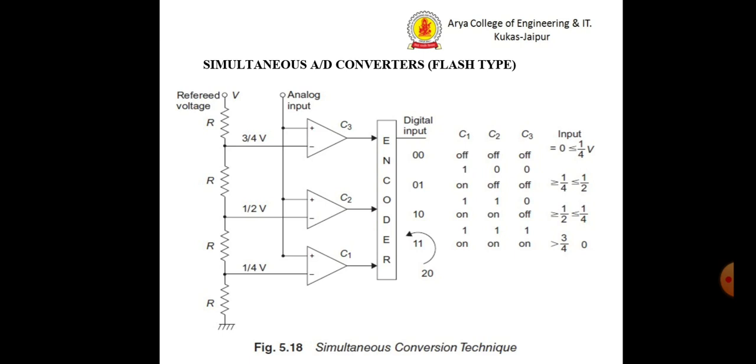The second disadvantage which can be listed is that the resolution is poor. It means voltage lesser than V by 4 cannot be detected in this particular case.